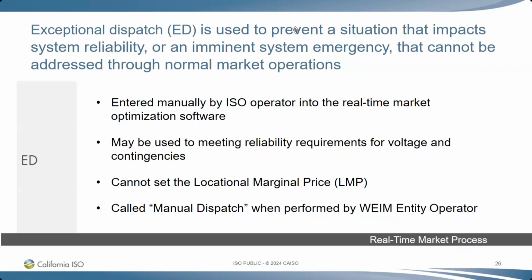Another question came in, or request, might want to give an example of three-part communications. So an example would be, let's say that Drew called you and said, this is Drew, Cal ISO, I need you to reduce your output 10 megawatts, starting at 10:05. And you would say, I hear you say that you need me to reduce my output to 10 megawatts at 10:02.